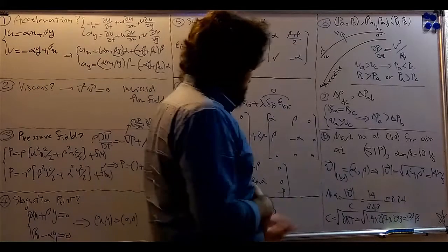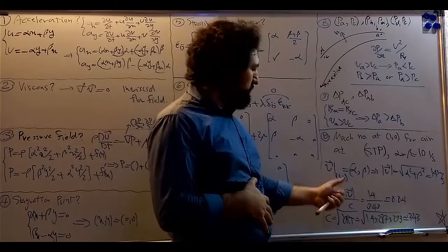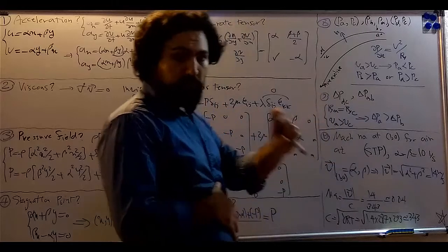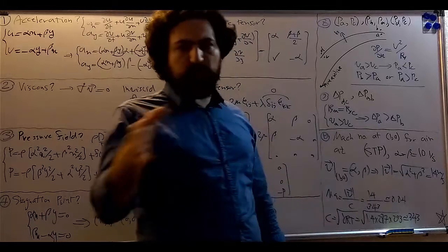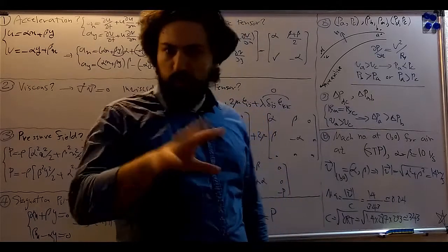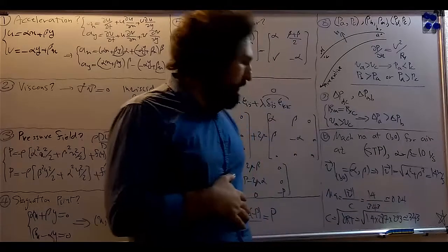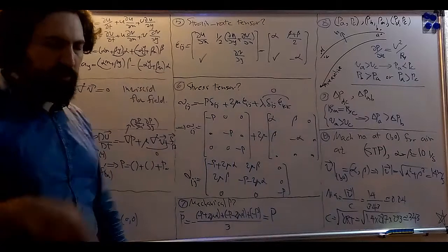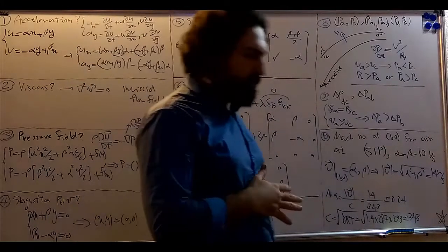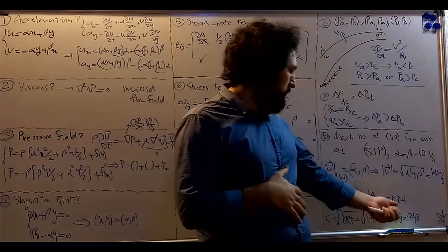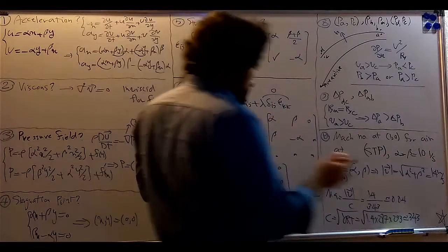And based on the definition of the Mach number, the Mach number equals the ratio of the velocity magnitude and the velocity of sound. The velocity of sound for a perfect gas, a calorically perfect gas with constant properties, equals the square root of the product of gamma, the specific heat ratio, the gas constant R, and the absolute temperature. In our case, it equals approximately 343 meters per second.